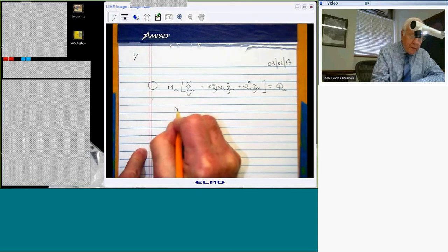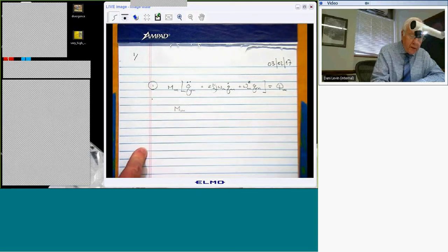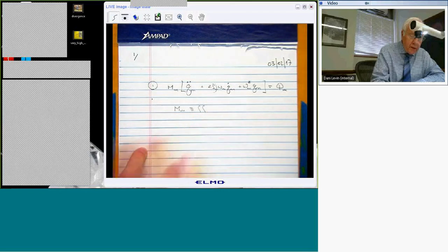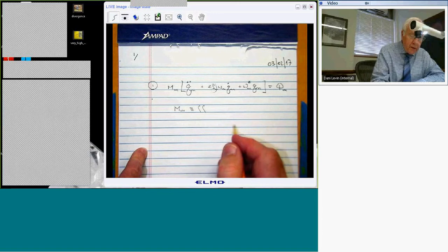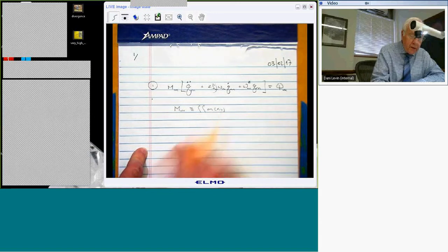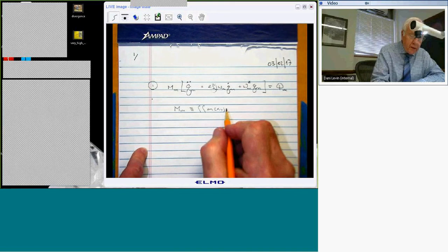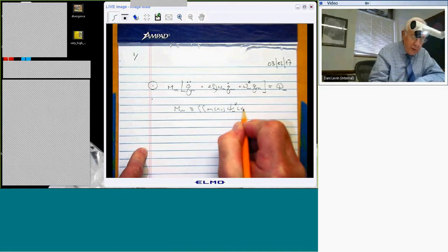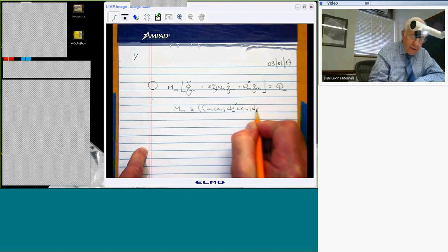So the generalized mass, and I'm thinking of a plate-like element, or at least a planar element, is defined as the integral over the area of this 2-dimensional object of the mass per unit area, which might depend on the coordinates x and y, times these wonderful functions squared, dx dy.